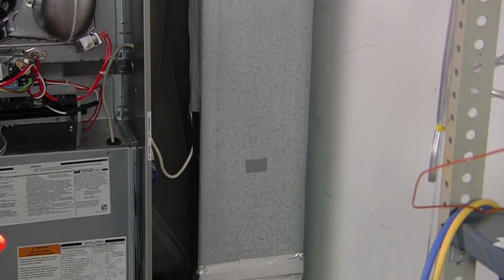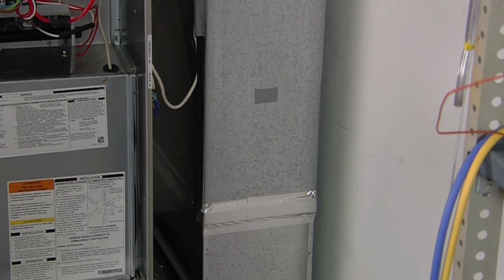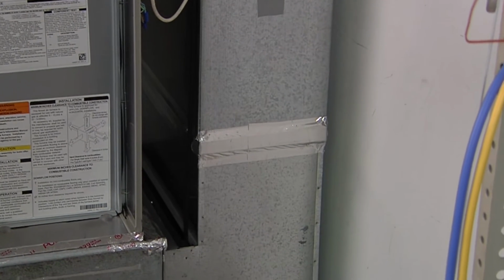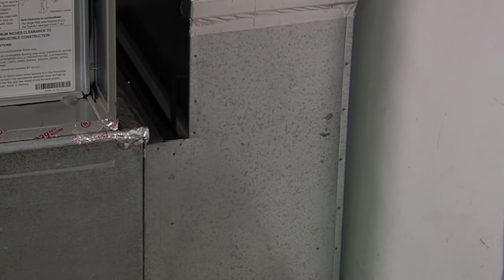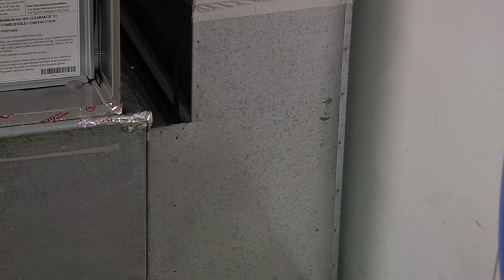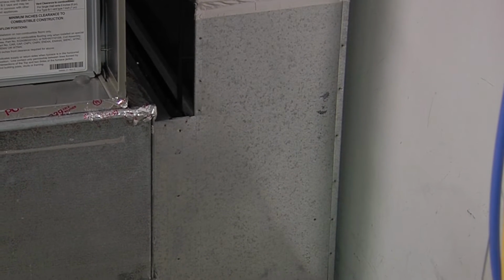It is important to take the velocity readings in a straight section of duct before any elbows or takeoff. The ideal location in many furnaces and fan coils is the return air duct right before the return air boot. If the return is a box connected to the furnace with branch returns, you can measure each branch return and add the results together to achieve the total CFM.